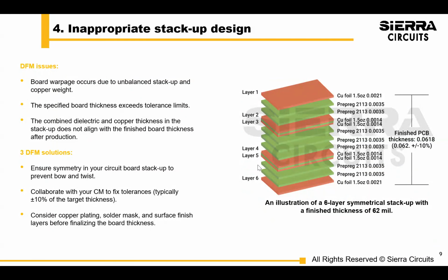For a manufacturer to onboard a material into their factory is not for the faint of heart. Not only do all the databases have to be updated correctly, but also the recipes have to be updated. So how are we drilling the material? What kind of plasma recipe are we using? Does it laser drill well? What's the scaling factor of the material? All these things mean that the fabricator has onboarded the material properly.